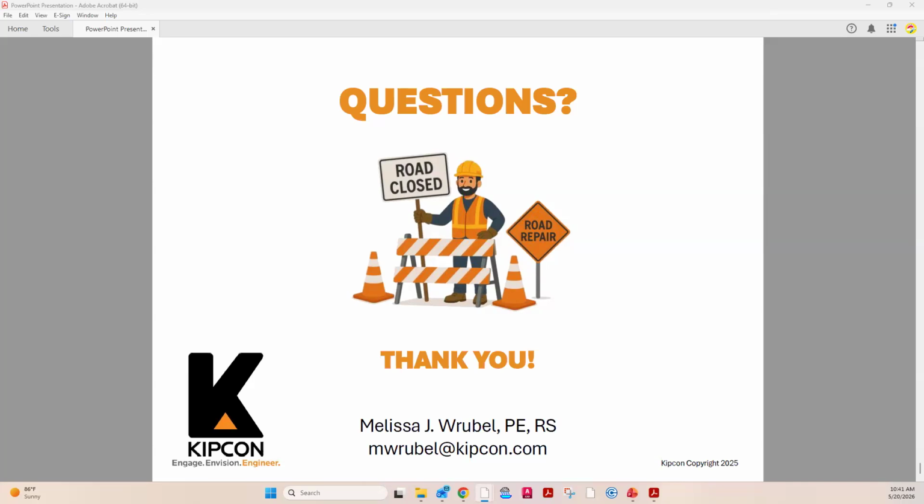I mentioned pre-construction meeting is very important. And also, the other key points are after the top course is milled to look at the base course, after the new top course is installed, and then a final walkthrough at the end to discuss any punch list items. So that's the bare minimum. That's what we recommend is the bare minimum. In phase projects, obviously, you're going to have more frequent site visits from your engineer, but those are generally the points that you want your engineer to have eyes on the project.